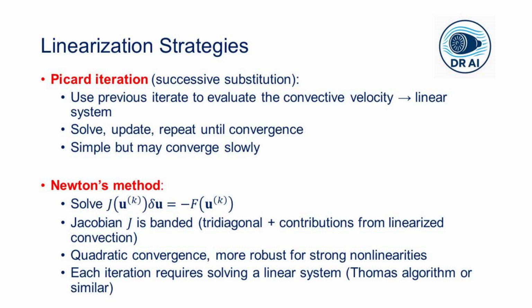So this approach of treating the nonlinear terms implicitly is at the heart of modern CFD solvers for the full Navier-Stokes equations. We often use implicit schemes for the viscous terms and treat the convective terms explicitly, or with a combination. But fully implicit methods, like the ones used in steady state solvers, rely on Newton iteration.